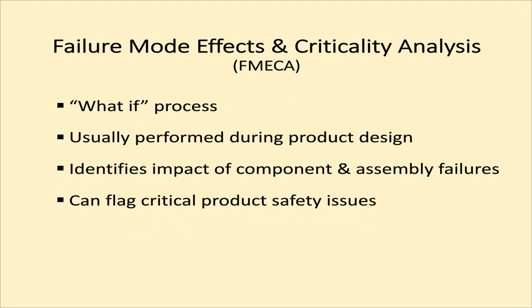Failure mode, effects and criticality analysis is a what-if process. It's performed during the product design, and the design engineers go through and identify the impacts of failures and what the result is. They might say, well, what if this component fails? What happens and what's the impact? What if this component and another component fail? What's the impact? It frequently flags critical product safety issues that can be identified and corrected in the design process.